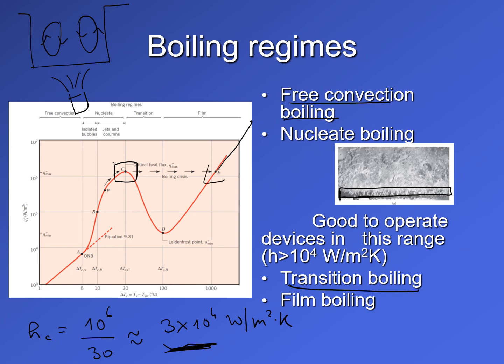But beyond point E, you are working with very large excess temperatures, which again is not desirable, because a very large value of excess temperature, that is a large value of the surface temperature of the rod, can result in melting. So point number C is the optimum point that you have, where the excess temperature is quite small.